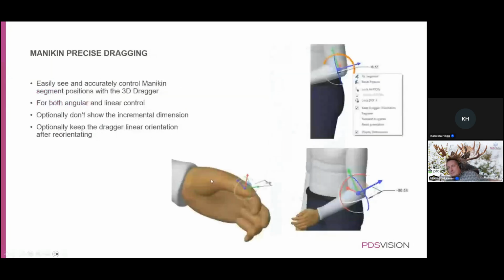Then tracking has been possible so far, but not necessarily so easy, since sometimes when you track, the whole body starts to move while tracking just the arm. Now there is a bit more control. First of all, you can define how much you want to move in millimeters and how much you want to move in angles. So individual joints can be manipulated. That's an improvement over the past one if you have to really fine-tune the mannequin position.